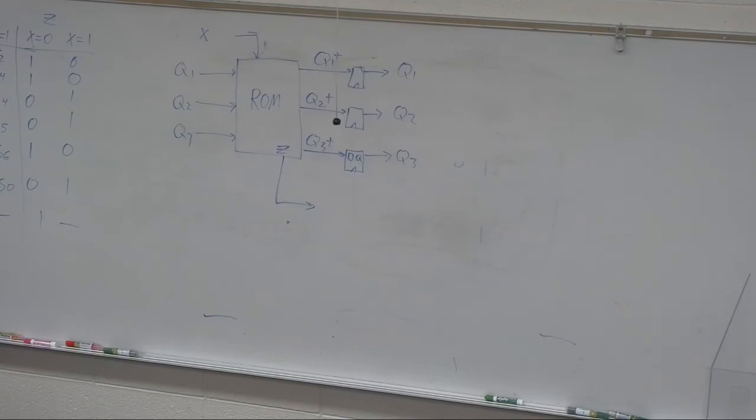What's the dash? It just means that it's a don't care essentially, in that this can't happen. If you were to be in a situation where you were in state 6 and you gave it a 1, it would be confused because that meant you hooked up the wrong logic as the input.